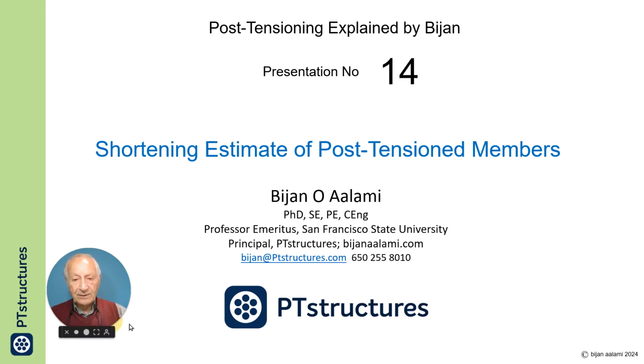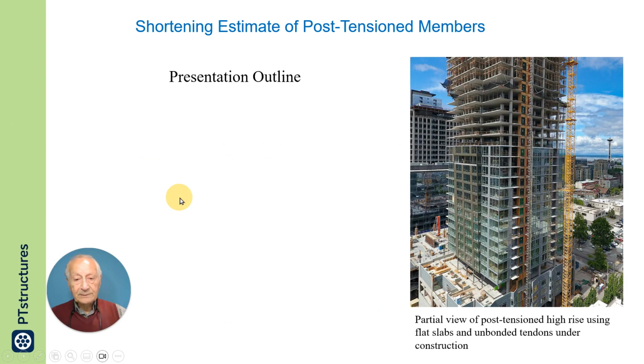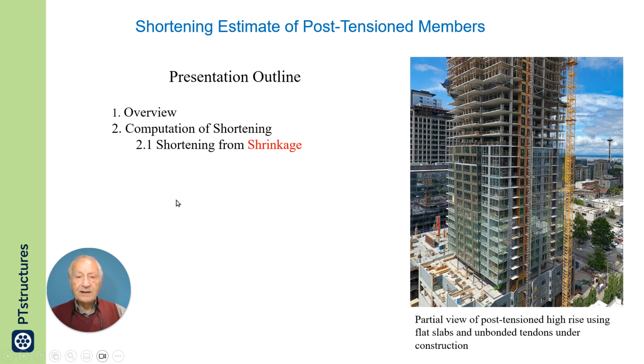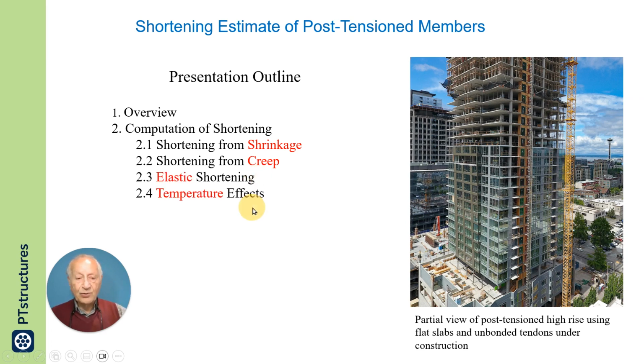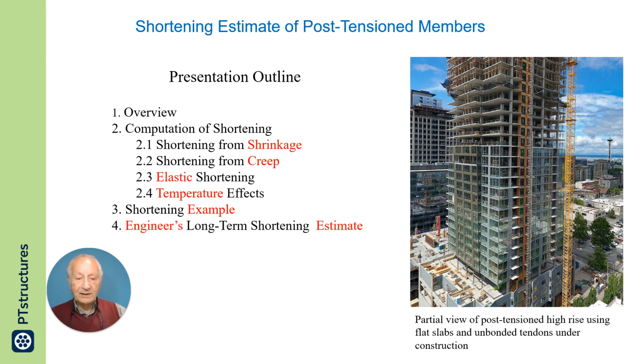Now, let us start. The presentation starts with an overview, computation of shortening, and it specifies that it is due to shrinkage, creep of concrete, elastic shortening, temperature effects, and follows it with an example of shortening calculation.